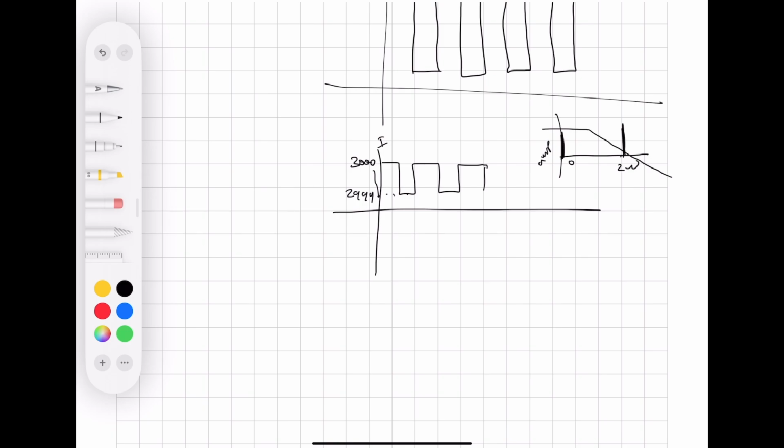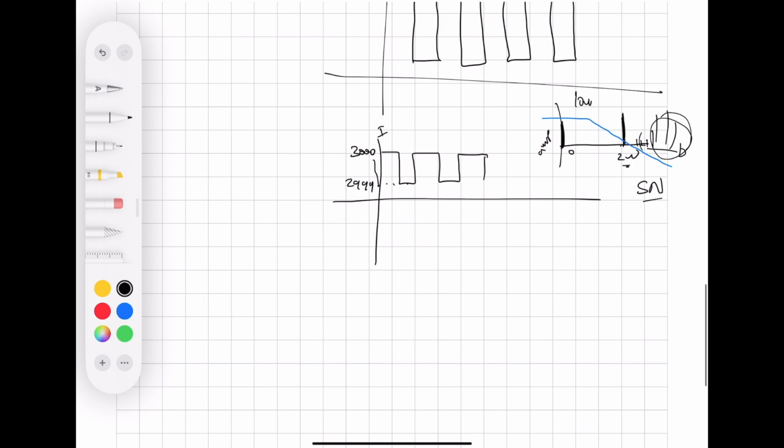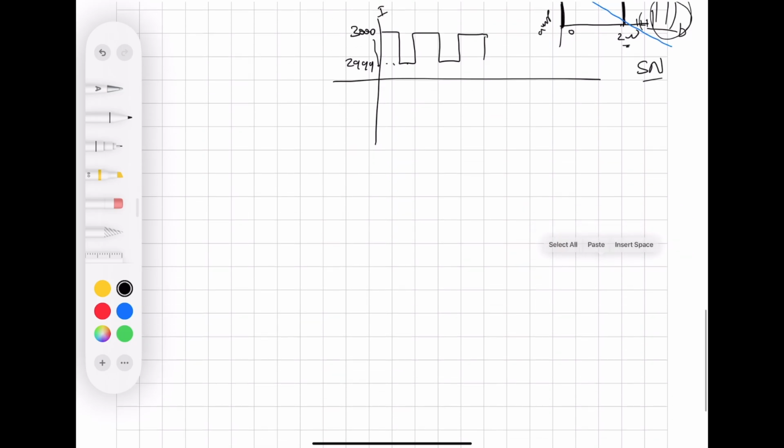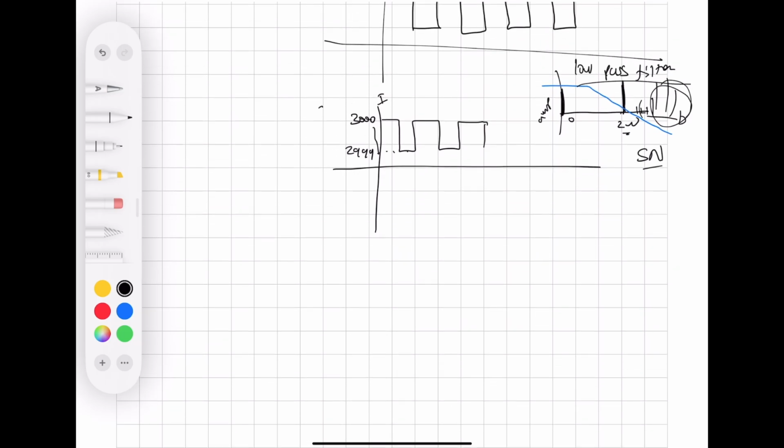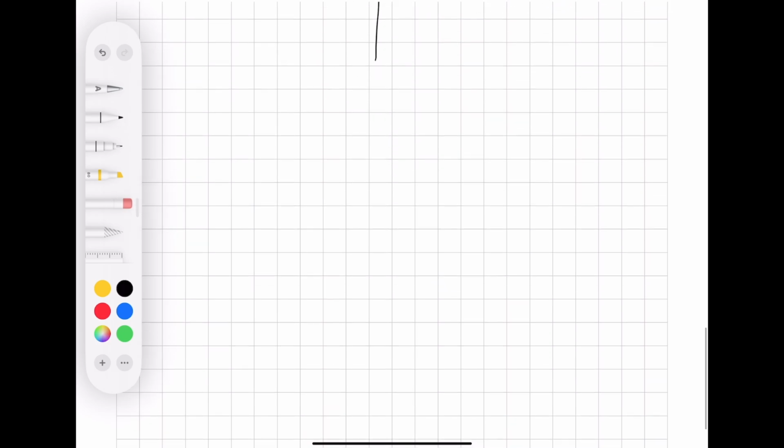That's how a low-pass filter is represented. It filters out the signal at 2 omega, because we don't really need that. At the same time, it also filters out other signals above this range, two birds, one stone. It filters out these higher frequencies in the same process, increasing the signal to noise ratio at the same time. So good things. This is the low-pass filter. It's very important. Now let's go back to our 3 and 4 amp example.